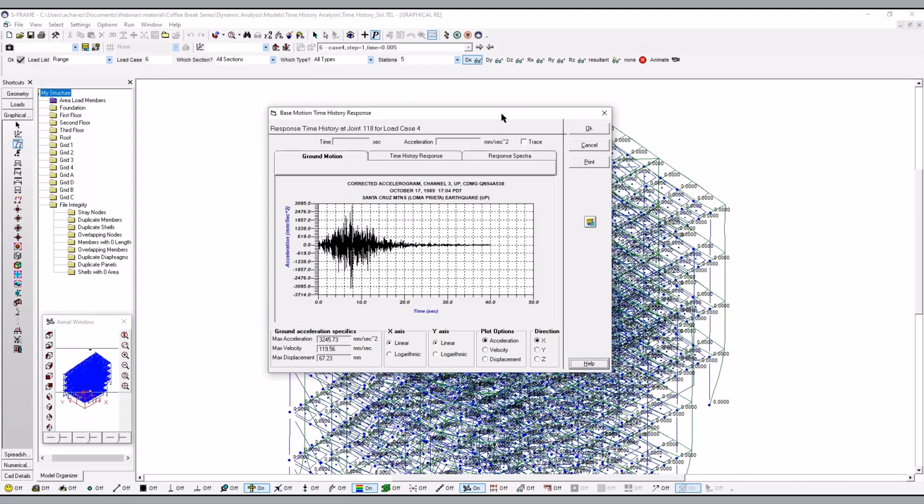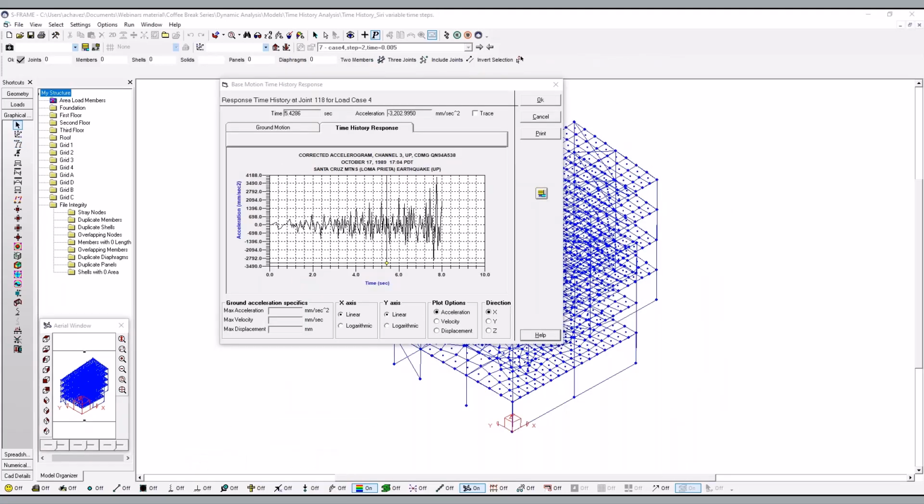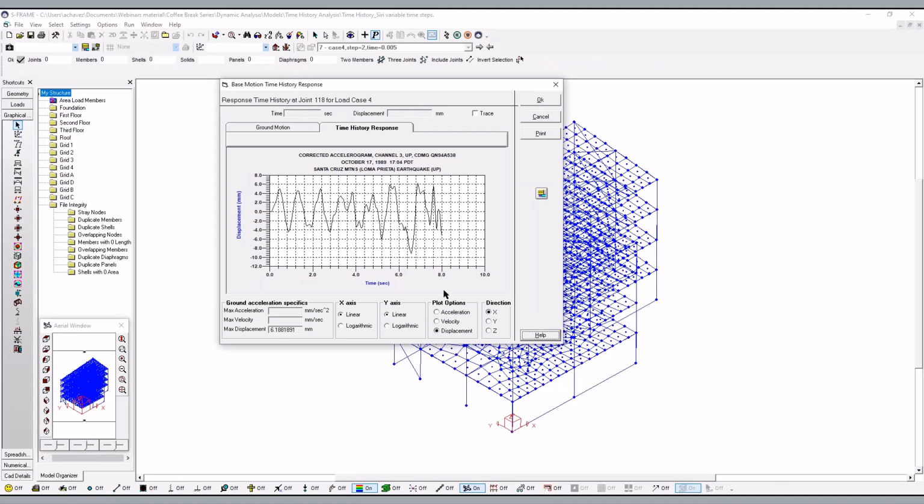You will immediately see that these are peaking and they are less distributed. They are lasting 10 seconds. It's a bit more, but the peaks are more exaggerated in this first model as compared to the second model over here. And the same applies, for example, if we check the displacements, they're going to be a little bit better represented in this case for our variable time step method.